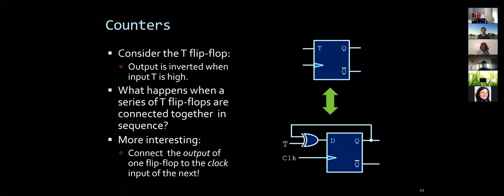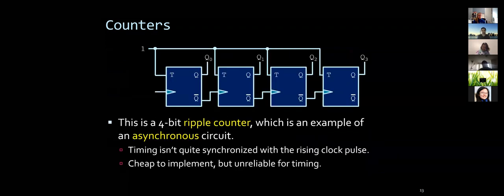So T flip-flops were not defined just for the sake of fun. They actually are interesting. You can connect them in a chain and, even more interesting, you connect the output of the flip-flop to the clock input of the next one. So let me show what I mean by that. Imagine that there is essentially this circuit that we have.